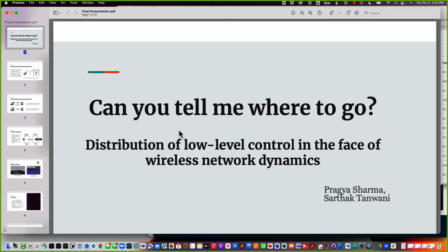So this project did a little bit of something I was talking about a few minutes ago, which is if I have a low level control like motor control. So how do we control motors? We sense the position of the motor and then control the voltage, and we use control algorithms like PID control. But if you look at more complicated control scenarios, like controlling a robot, then it could be a more sophisticated control.